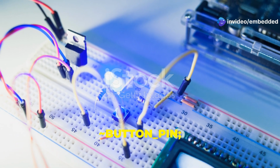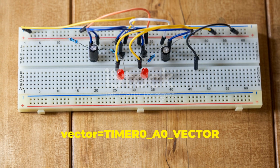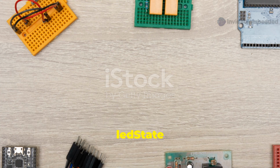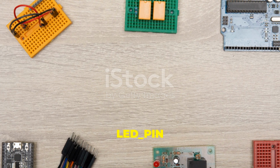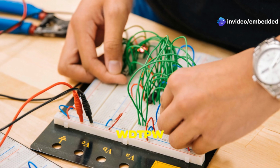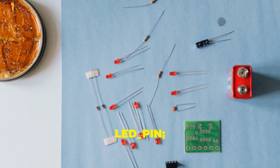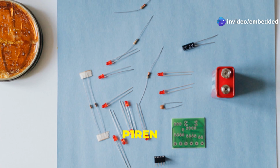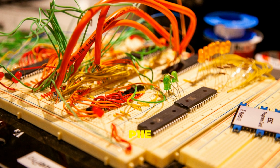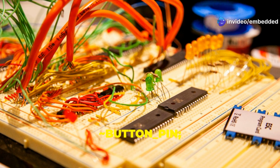Clear the interrupt flag: P1IFG &= ~BUTTON_PIN. Timer interrupt service routine: #pragma vector = TIMER0_A0_VECTOR, __interrupt void Timer_A(void). Toggle the LED state every 500 milliseconds: if LED_state, LED_PIN = 1, else LED_PIN = 0. int main(void): stop the watchdog timer, WDTCTL = WDTPW | WDTHOLD. Configure LED and button pins: P1DIR |= LED_PIN, P1DIR &= ~BUTTON_PIN, P1REN |= BUTTON_PIN, P1OUT |= BUTTON_PIN. Configure button interrupt: P1IE |= BUTTON_PIN, P1IES |= BUTTON_PIN, P1IFG &= ~BUTTON_PIN.